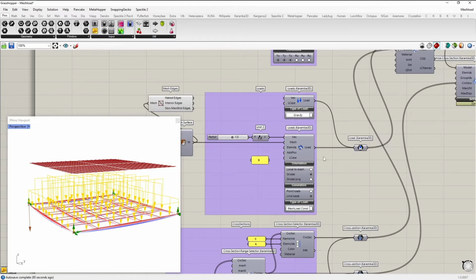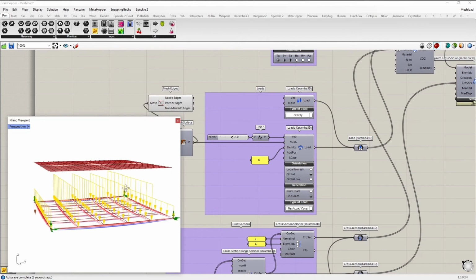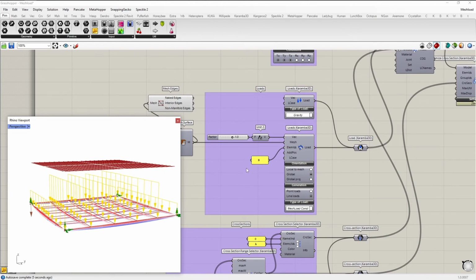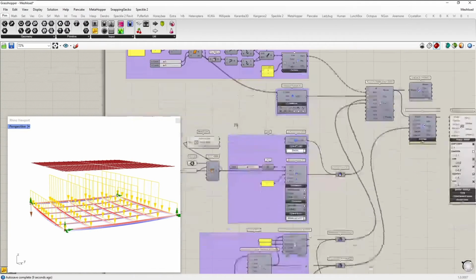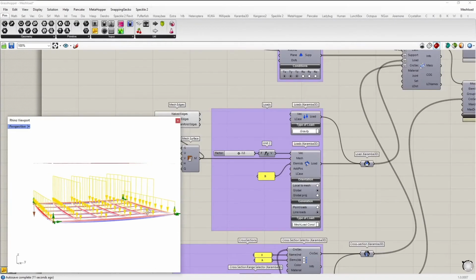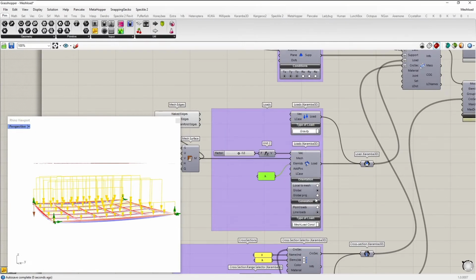With this mesh load component, and because we split it up into A and B cross-sections, we can then use the element ID to just generate mesh loads onto the B beams. And the same goes for the A direction.